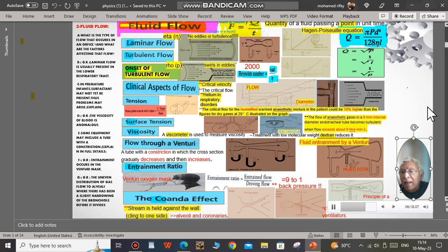Its pressure is decreased, so this is correlated to the potential energy, so that to keep the energy, the kinetic energy must increase and the velocity increase. So at this constriction we have a low pressure, as you can see from the manometer, and a high velocity.